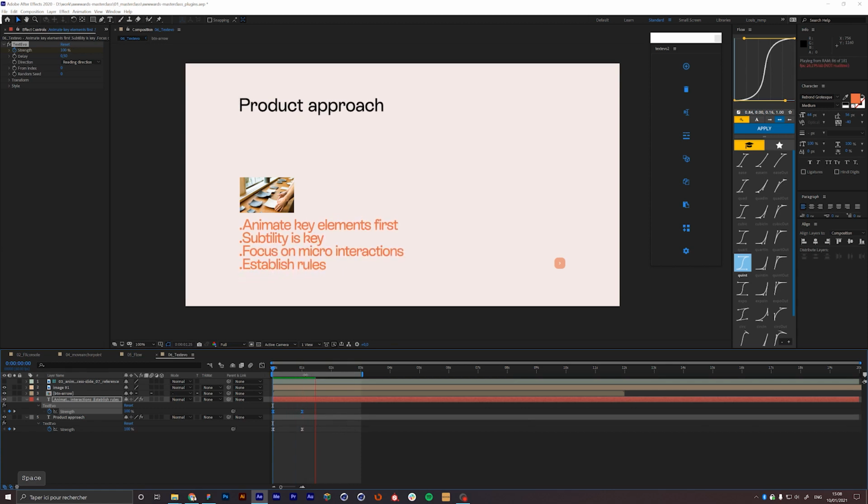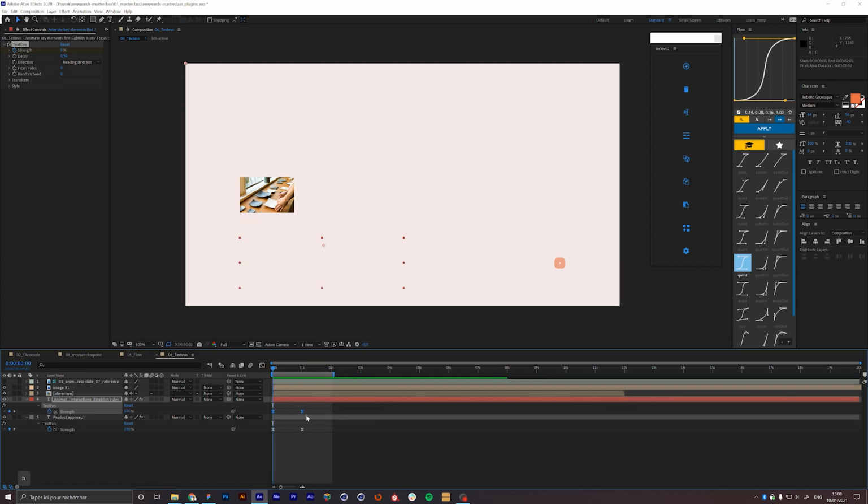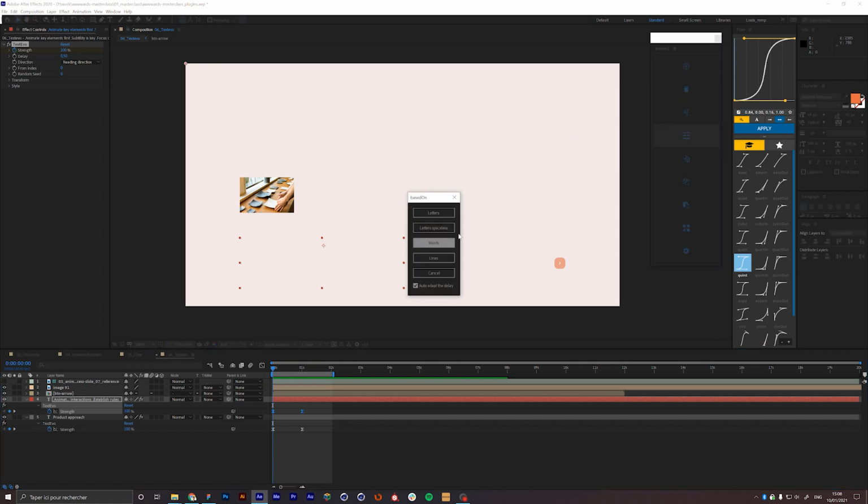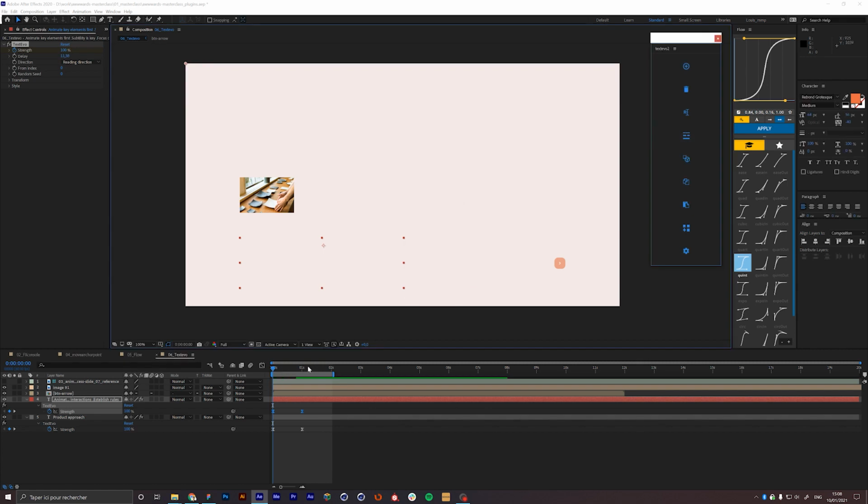And it's pretty nice, but the animation takes too long because there is a lot of text. So what I'm gonna do first, I'm gonna reduce the preview area, and I'm gonna put the end of the previewing area by hitting the end button, and I'm gonna go here and change based on mode, and here you can see that you have several options, and I'm gonna hit the line button, and now let's see.